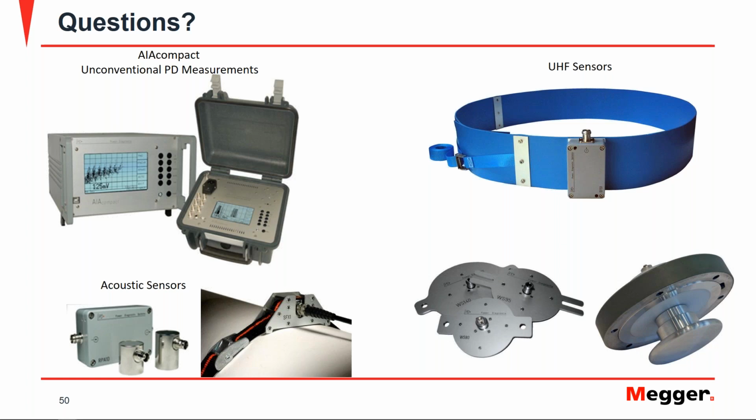But they also offer a lot of benefits. If you have a critical asset, or if you have performed measurements on an asset and determined that there is a defect and you want to keep a closer eye on it, you can install these permanent monitoring solutions that allow you to monitor partial discharges 24/7.